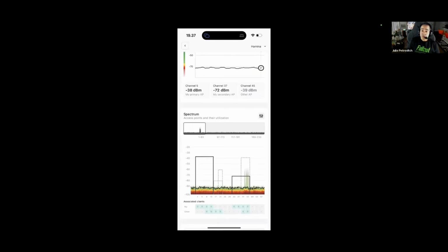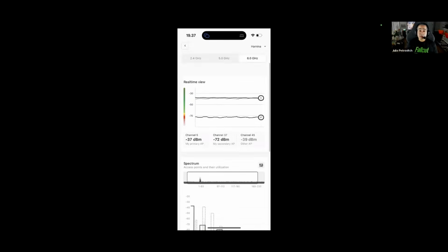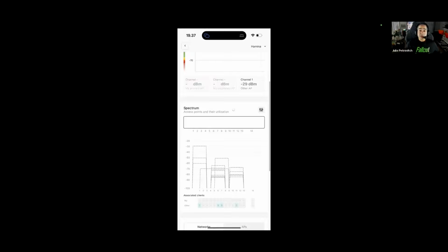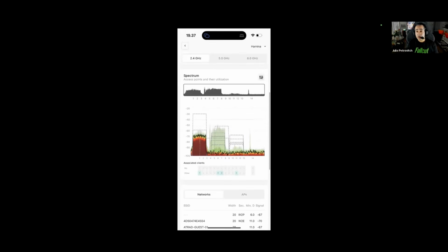On the AirCheck G2, besides being able to see utilization, both Wi-Fi and non-Wi-Fi, similar to what you showed earlier, the Wi-Fi chipset available on the G2 also had the ability of identifying non-Wi-Fi interferers. It wasn't a spectrum analyzer, but it could tell you if there was a microwave oven or a Bluetooth device and so on.